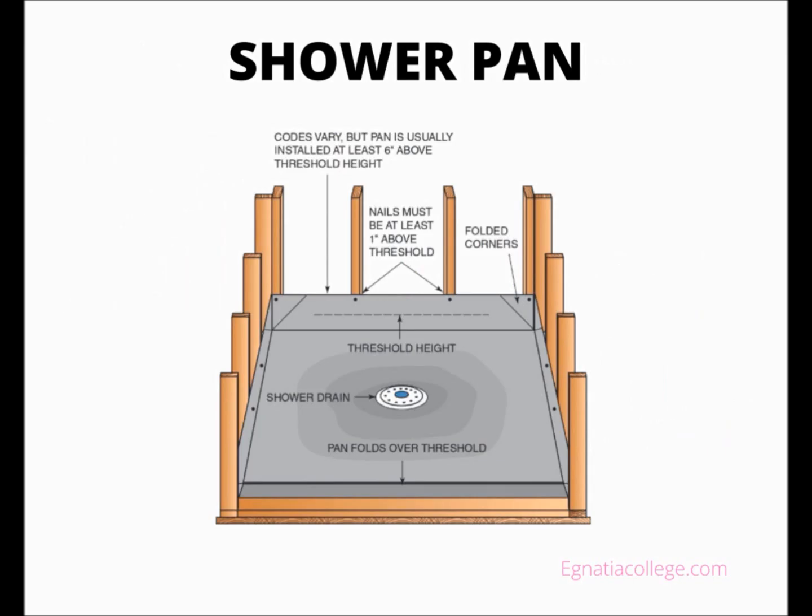Shower pan. A shower has a P-trap similar to a washing machine. Some codes allow a 1½ inches trap to connect a shower, others dictate a 2 inches minimum trap size. The drain assembly for a one-piece shower unit or a pre-molded shower base is typically provided with the unit. The piping exiting the shower floor is connected with a P-trap located below the floor.